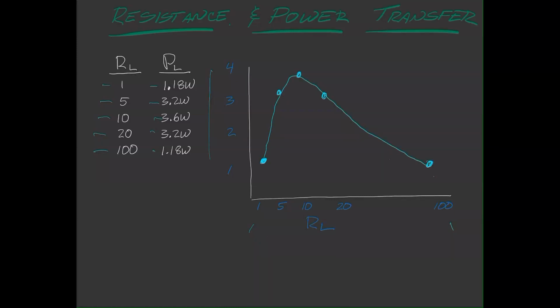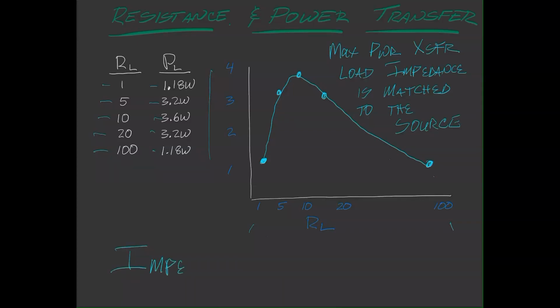What we've done here mathematically is we've just demonstrated that maximum power transfer occurs when the load impedance is matched to the source. And this is why terms like impedance matching are such a concern in circuit design.